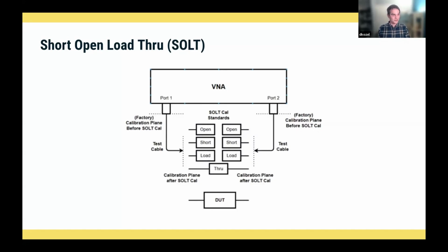Although, for fun reasons, often it's actually a couple of 100 ohm resistors or 200 ohm resistors split across, because you can get lower capacitance and lower inductive imperfections that way. So consider it a perfect 50 ohm resistor for the moment. All of the power sent into it will just vanish if everything else in the system were perfect.